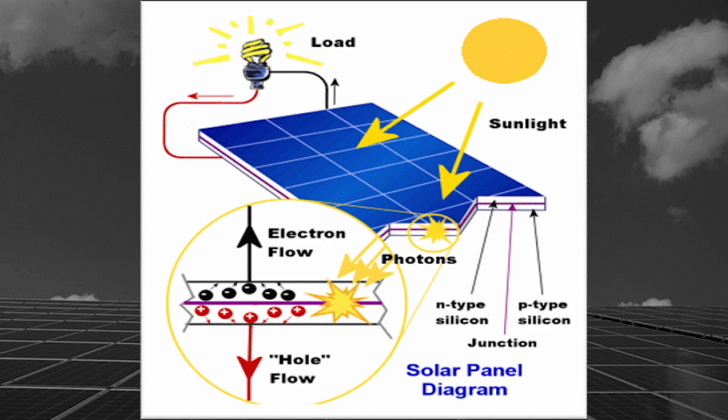Since crystallized silicon is not a good conductor of electricity, some impurities are added intentionally, and this process in which impurity is added is called doping. The bottom layer of the PV cell is doped with boron, creating a positive charge. The top layer is doped with phosphorus, creating a negative charge. The surface between the p-type and n-type semiconductor is called the p-n junction. Sometimes it is also called a junction diode. The movement of electrons from the p-type layer to the n-type layer results when sunlight gets absorbed at the p-n junction.